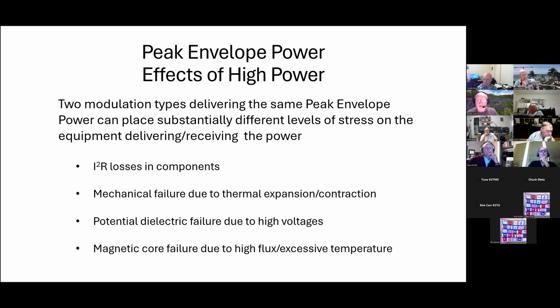And it's going to heat up because of its internal resistance. And when it heats up, if its design is such that it can't dissipate the heat that's being produced by it, components can melt. The solder that holds it together can melt and flow, and you become an open circuit. The material that makes up the dielectric, when it's heated, its properties can change. So you can destroy capacitors with large amounts of RF power.